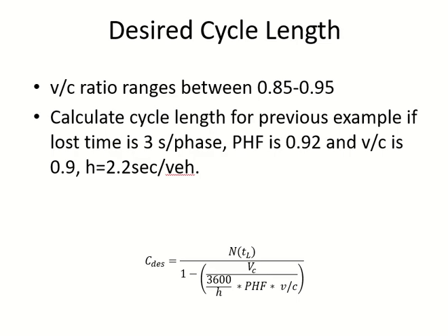So when the actual cycle length is so low, close to a minute, then you round it up to the nearest 10 seconds, not to the nearest second. Got the point? If it was already 150 seconds, then I will round it up less. But it's already very low, so I will round up more because I have more margin. So we will make it 70 seconds.